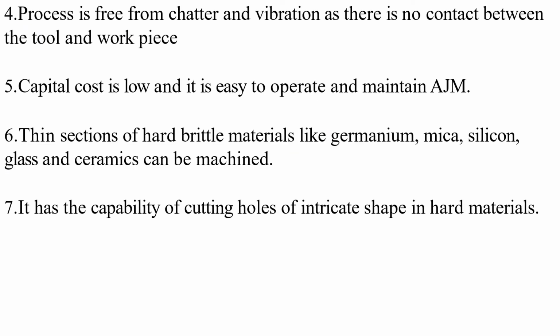The process is free from chatter and vibration as there is no contact between the tool and workpiece. Capital cost is low and it is easy to operate and maintain abrasive jet machining. Thin sections of hard brittle materials like germanium, mica, silicon, glass and ceramics can be machined. It has the capability of cutting holes of intricate shape in hard material.